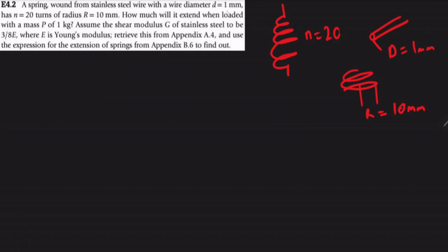So they said, how much will the spring extend if you add a mass of 1 kg here? By how much will it extend? It's like the former question that we did. How much will it deflect? This is how much will it extend. So this is straightforward as well. They told us to get the formulas. Assume that the shear modulus is given by 3 over 8 E, where E is the Young's modulus, and they told us to get the formula for